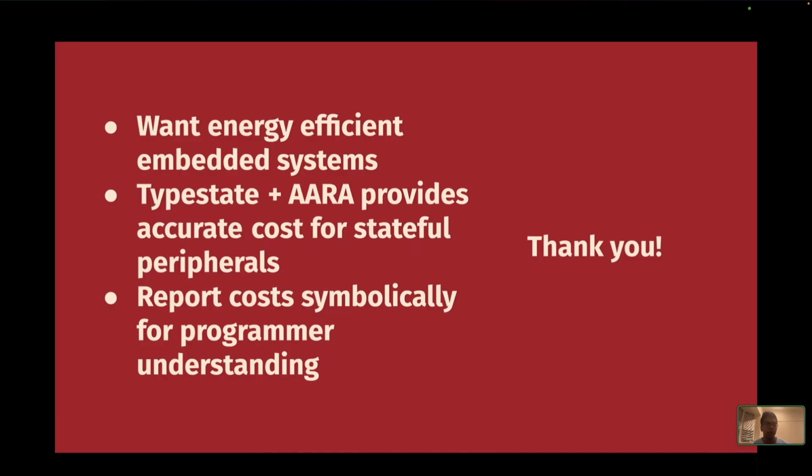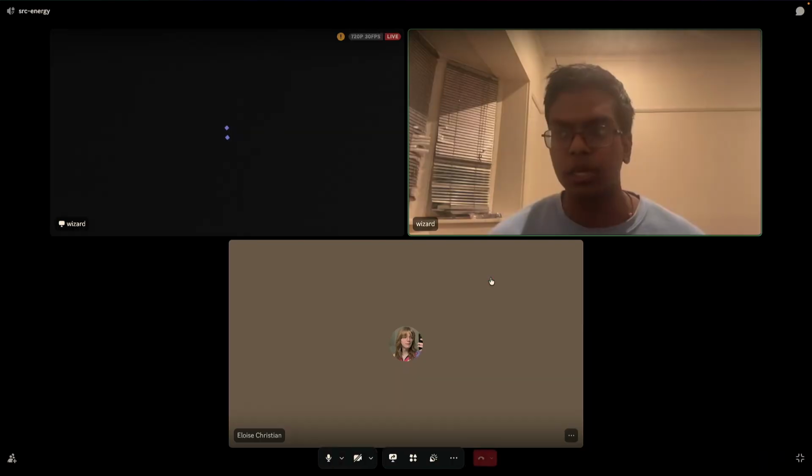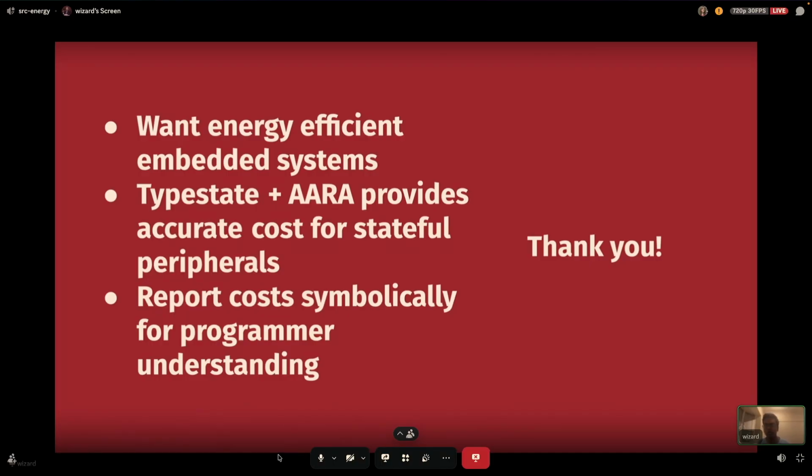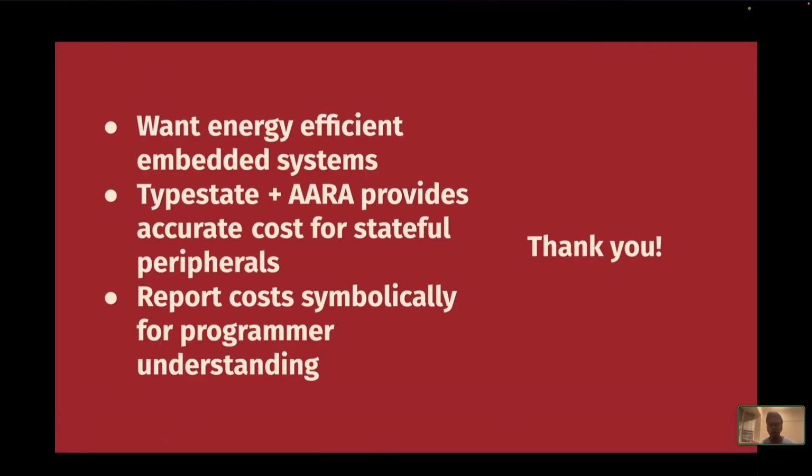Many low-power embedded systems, we can actually assume deterministic timing for each of these instructions, and the system can track the timing information for each statement. And then, of course, for function calls, a function is a collection of statements, and so each function call also has associated with it a timing summary, which represents the time that each statement in its function executes. And we incorporate this with our costs that we report.